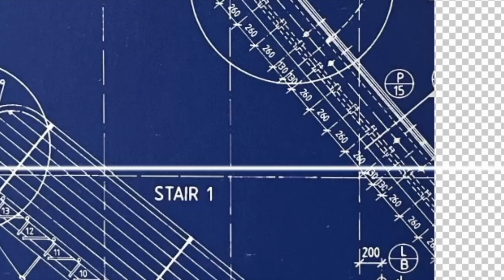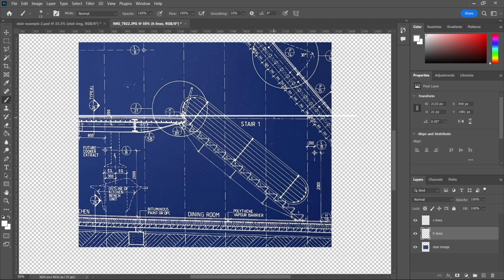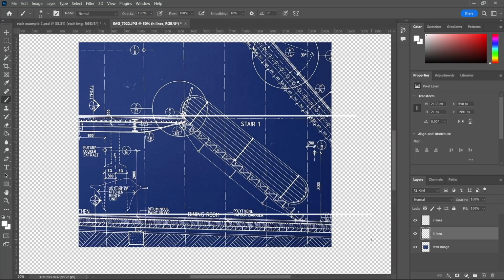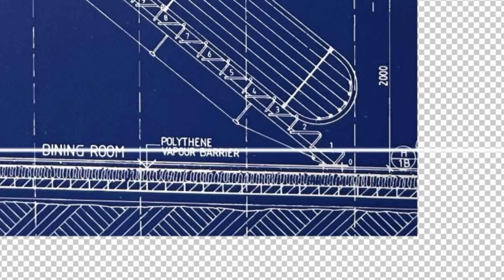As you can see, the grid line is not actually lining up because the image is skewed. So we'll do the same thing at the very bottom here. Click shift, and whoops, you see that I didn't actually finish my line. So I want to Control Z that, click enter. Now that the line should be ended, that's why you had that diagonal line. I will click shift down here, and you'll see that it's definitely not straight at the bottom. So click enter again to get rid of that.